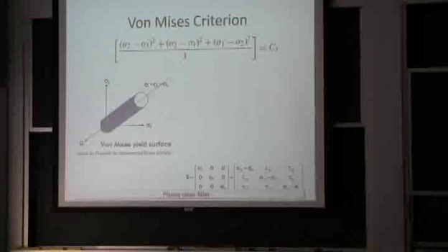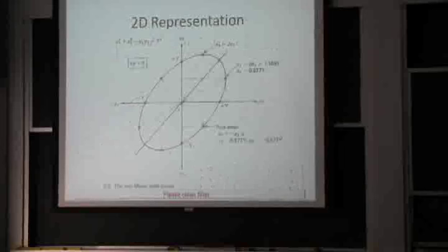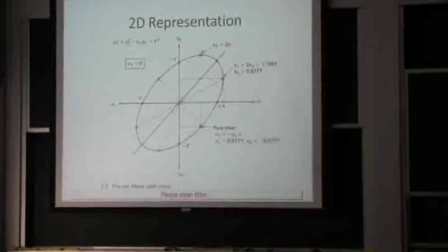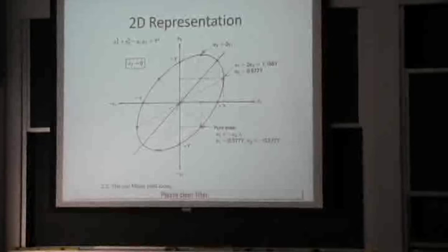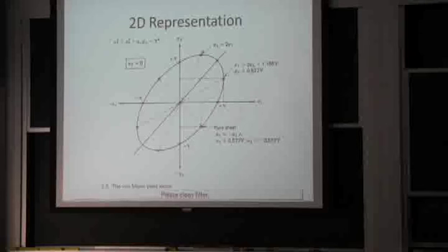The von Mises ellipse is just a plane skewed through this hydrostatic cylinder. You got your von Mises ellipse, there you go. That ellipse is just a piece of that cylinder. The hydrostatic component, sigma 1 plus sigma 2 plus sigma 3, has nothing to do with deformation processing, except that it can suppress fracture. And people do things like hydrostatic extrusion, and they can extrude brittle materials that otherwise would fracture if you tried to just push them out of a toothpaste tube, right?